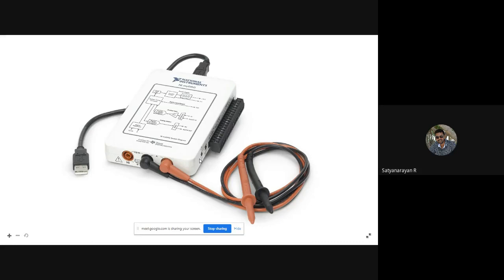Why? Because of the voltage or the capacity you pass from your sensors or any of the loopback circuits. If you use a multi-strand wire, there is a possibility of voltage drop. That's why I recommend using a single strand wire instead of multi-strand.